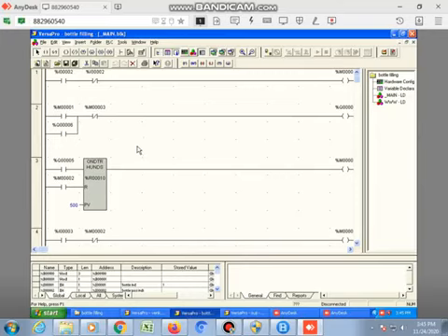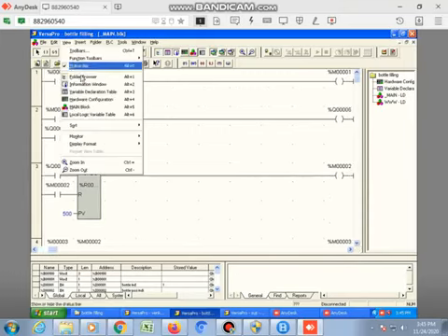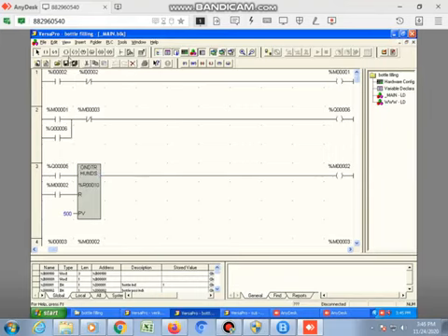bottle filling system. In this you can see the first two I told you, these are two inputs, I1 and I2. These two inputs are for overhead water control. I1 and I2 are for water level control. When it reaches the total top, when it is full, then it will be off and the motor is off, and when it is not full, it will be open. So here we are using a timer for the filling system. We are using an on delay timer, which has a register address, and we will be using a memory address.